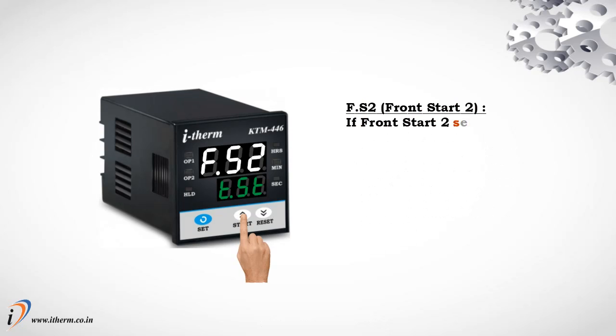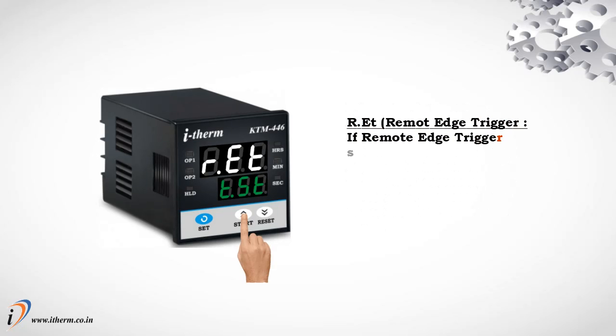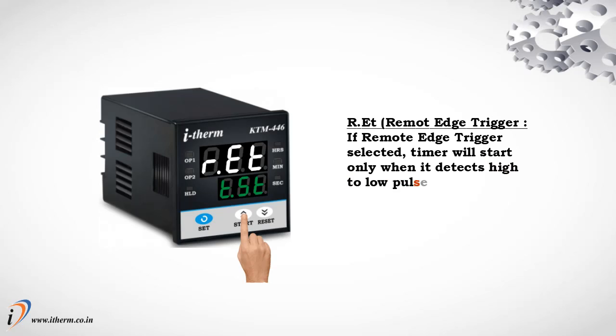Front start 2. If front start 2 is selected, the timer will start only after the user presses the start key. If power fails in between the cycle, on next power on, the cycle will start after applying the start command again. Remote edge trigger. If remote edge trigger is selected, the timer will start only when it detects a high to low pulse at the back terminal from external input.